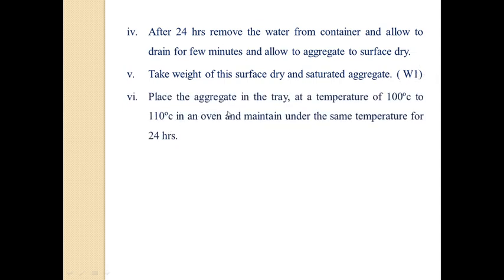Next, place this aggregate in an oven at a temperature of 100 degrees Celsius to 110 degrees Celsius and maintain the same temperature for 24 hours.